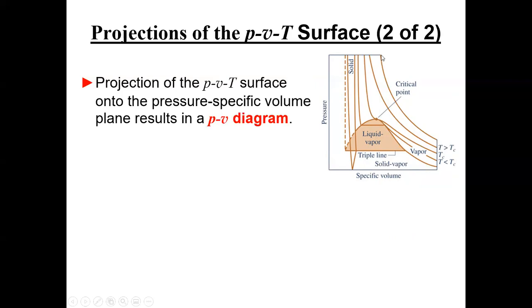The ideal gas law would probably do a good job characterizing states along this line. Not so much over here, where you see this kind of bump caused by the presence of the liquid-vapor dome. So the ideal gas law without some correction is not probably very good for these vapor states out in here and maybe even up in here. Okay, so we'll talk more about that.